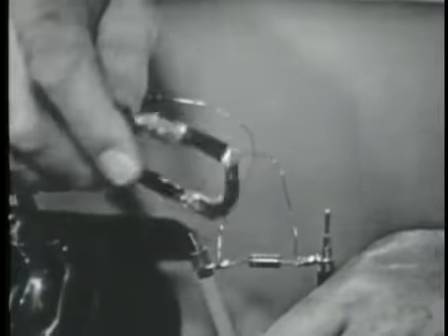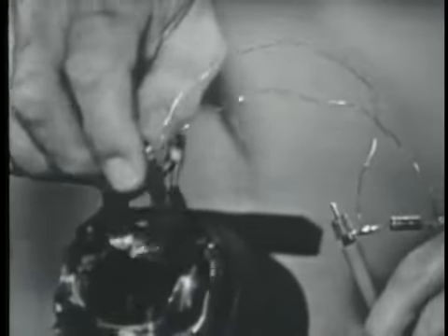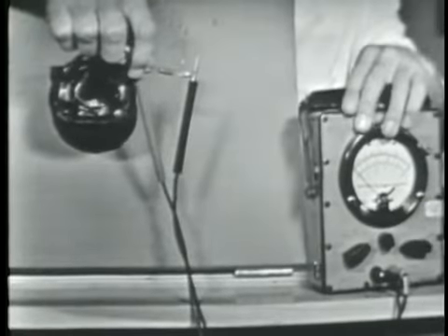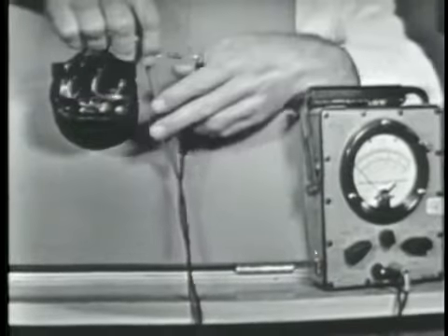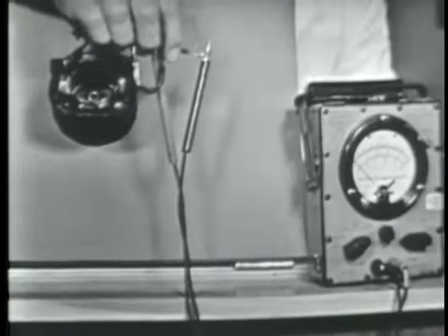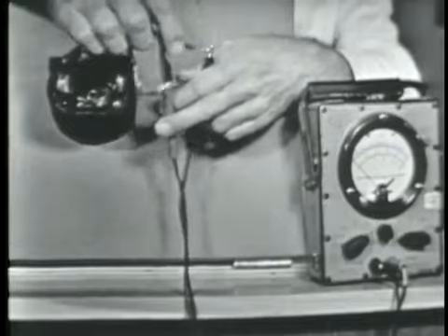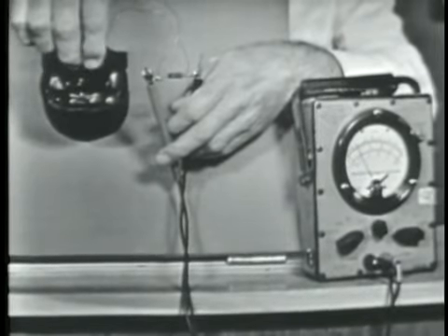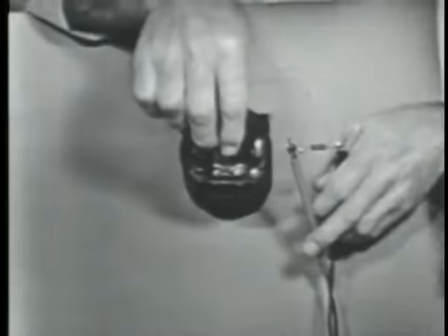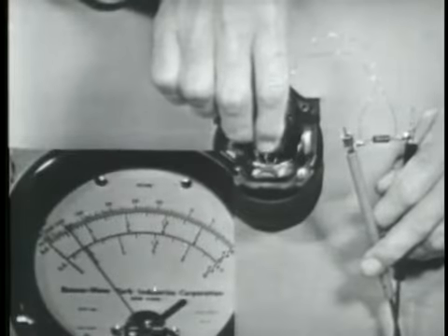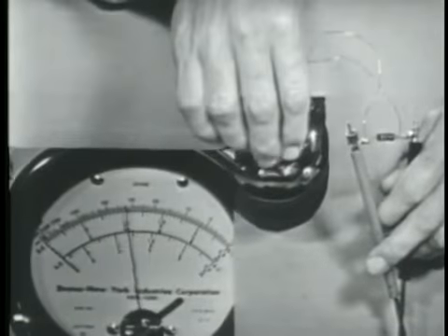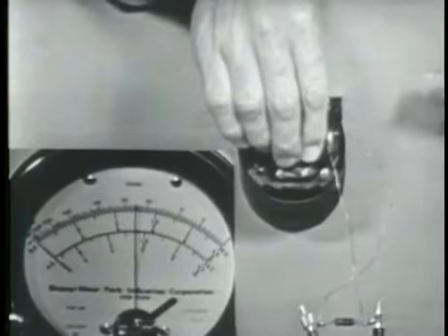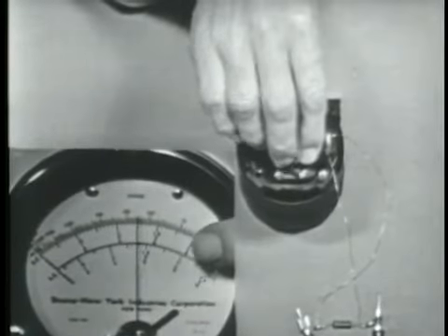Okay. All right, now I'm going to take the loop of wire and place it in the field windings. Now I want you to watch the meter on the PSM6 here. Now, let me apply the juice first. You may hear a little hum being picked up by the microphone because of this magnetic field. Now, as I place this loop of wire into the field windings, like this, you'll see something there. There it is. The PSM6 indicating a voltage value. That's induced voltage, huh? That's right. That's the induced voltage from this loop.